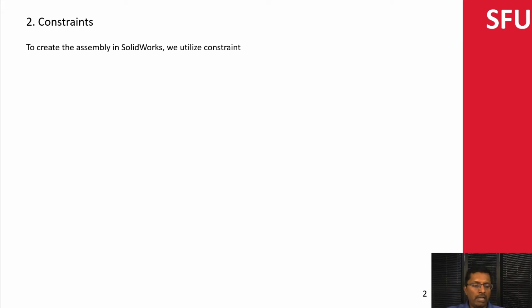Essentially, if I have a hinge, I can set up a constraint so that it is always going to be rotating about the hinge point. If I have a door, I can set up the constraint so that I fix the hinge to the door, virtually gluing those parts together, or have another type of constraint which enables relative rotation or relative translation in one direction or the other, to do more complicated limitations on the degrees of freedom, which is what the constraint actually does.